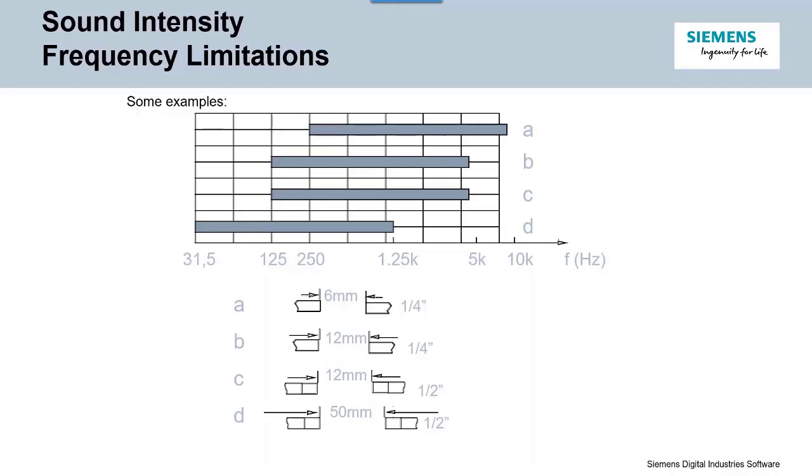Just to add on that point by Raj, that spacer is due to wavelength. As I go lower in frequency, my wavelength is longer. Yep. So I need more space between the microphones to capture that larger wavelength that would correspond to a lower frequency. And the converse is true for higher frequency. I would need a smaller spacer to capture that shorter wavelength appropriately for the higher frequencies.